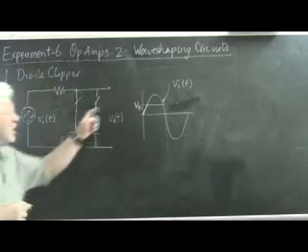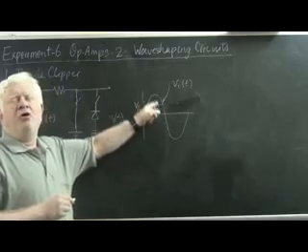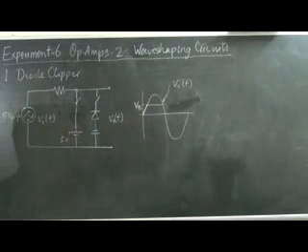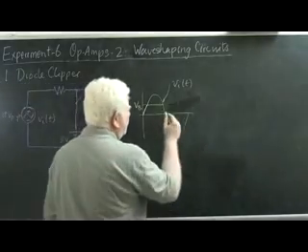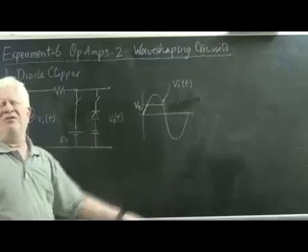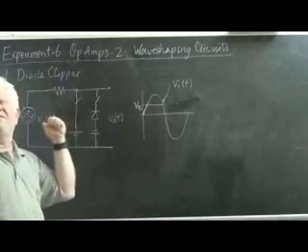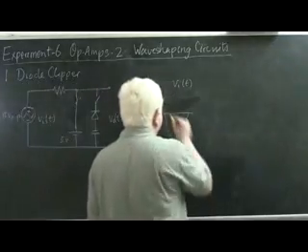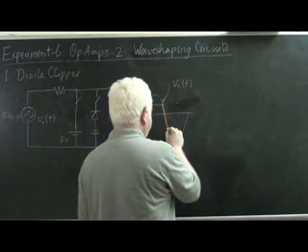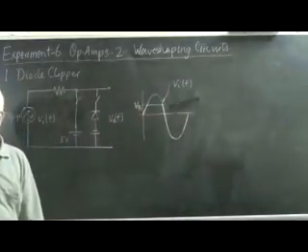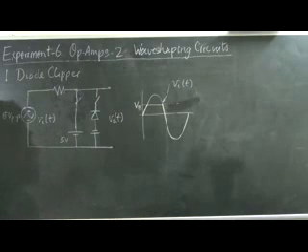However, when the input curve starts falling and lowers itself to below VB, again this diode becomes open as we showed you earlier, and the output voltage mirrors the input voltage, reflects the input voltage. So for all these rest of the time instants, where the input voltage is less than VB, all we get at the output is a copy of the input. So we will get this. This then is the upper side diode clipper.